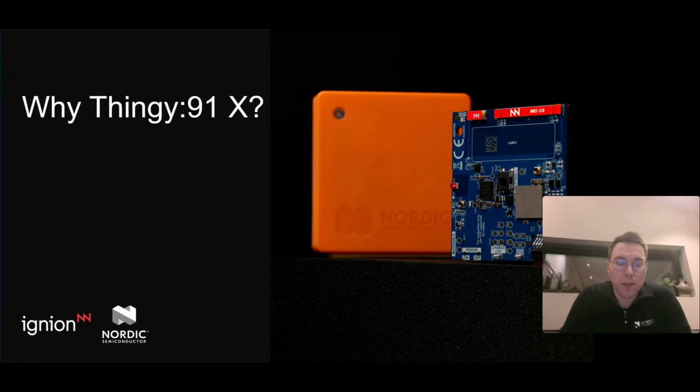this successor, things can be challenging with regards to the antennas, because the antenna is also one of the most important parts of a wireless device, especially for cellular. This impacts the quality of the communication, and also, of course, power consumption. So if you have done a bad antenna design, this could mean that you are not able to communicate with your device, or that the device would use a lot of power and burn up the battery.